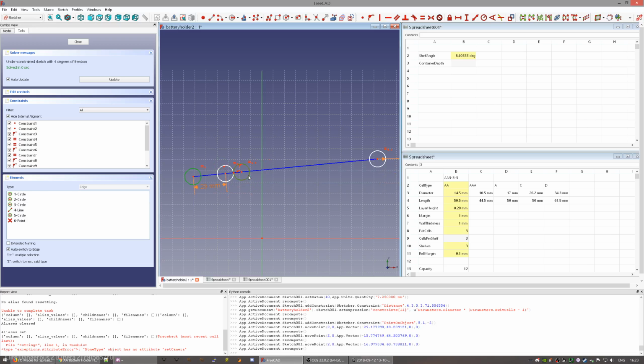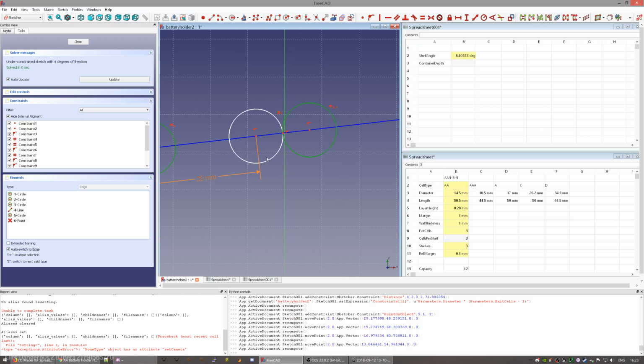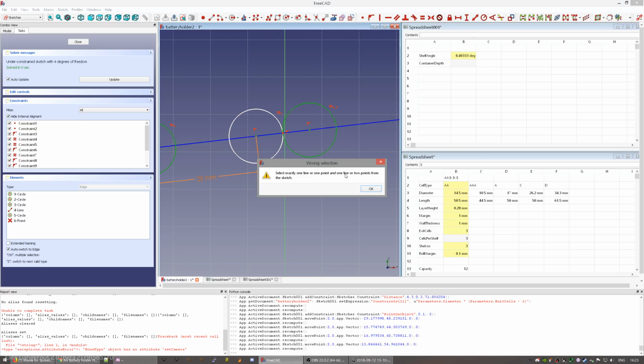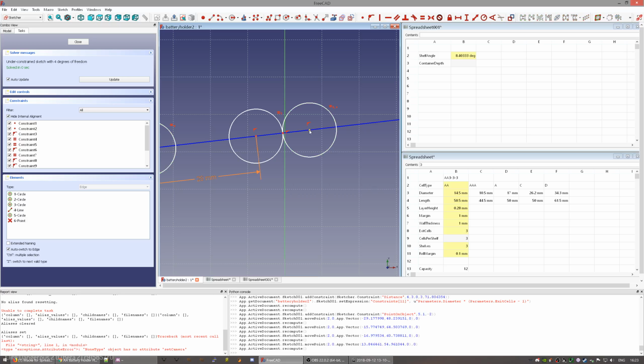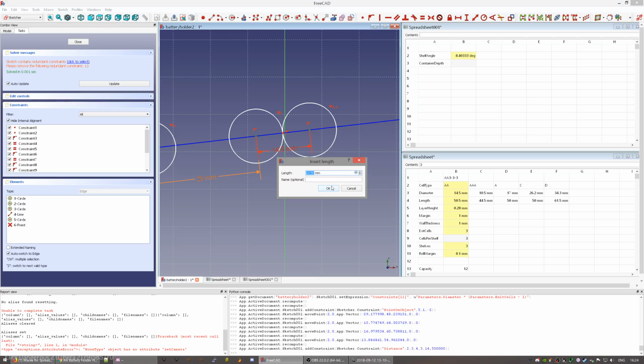And it may be easier to drag this closer. So that's one of the inversion problems that you may see at various points. One of the solutions here is to constrain this distance as well, but this I think is an over constraint.